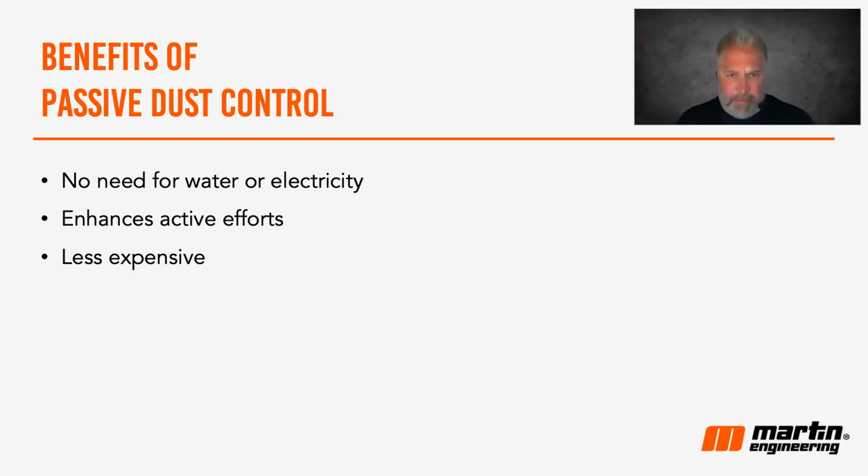If you're using some sort of suppression system to control dust, another active method, that's going to rely on water, maybe water that's treated with a surfactant or a chemical to make that water more effective in controlling that dust. There's a big problem with adding water to some operations. The biggest problem that we see with adding water to your material to control the dust is that if you're in an aggregate or a mining facility and you're screening materials, that material with that added moisture can stick to screens and blind screens off.